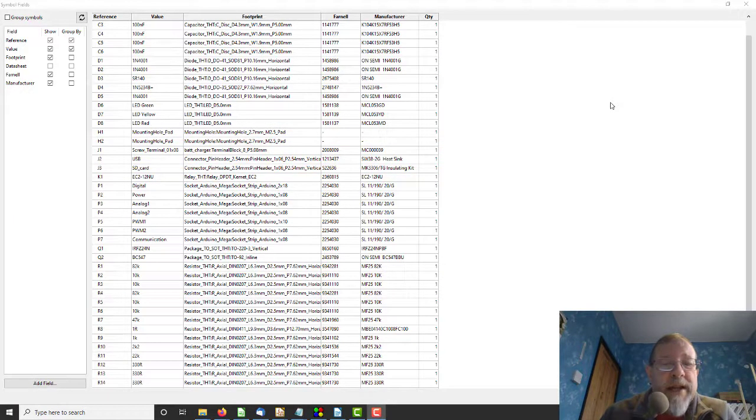So that leaves the heatsink and the mounting kit to attach the transistor to the heatsink and insulate it, which are on the BOM but don't have footprints, and that in KiCad is a bit of a tricky thing to do. So pro tem, I have just added them to these two sets of pin headers, because they're not actually pin headers.